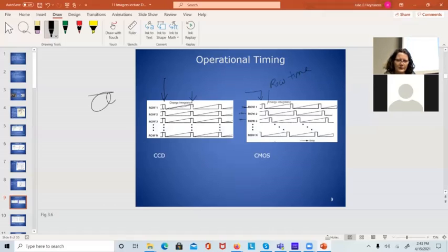I was the timing person. And then we would wait, and when the integration time passed, we may be on row 434. So when we get to when we reset row 434, we go back and we read out row 1. And then we reset 435 and then read out row 2. Okay. And so you're going to have the same integration time on each row in the image, but you can start resetting them a little bit earlier. And again, you're comparing its reset value to its final value. It waits and then it gets read out.